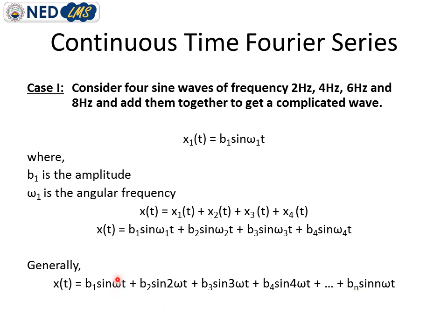But frequency is represented in terms of fundamental frequency or fundamental period and integer multiples of this frequency, which is omega, 2 omega, 3 omega, 4 omega. However, it is not necessary that all these integers must be present, that 2 omega must be present in that signal. Maybe the signal is not of that shape; it may contain 2 omega, it may contain 3 omega, 5 omega, 7 omega, it may only contain odd harmonics, it may only contain even harmonics, or it may contain even plus odd harmonics. So it depends upon the nature or shape or pattern of the signal, which frequency contents are present in that signal.